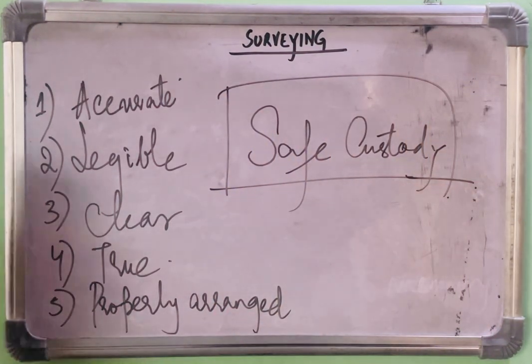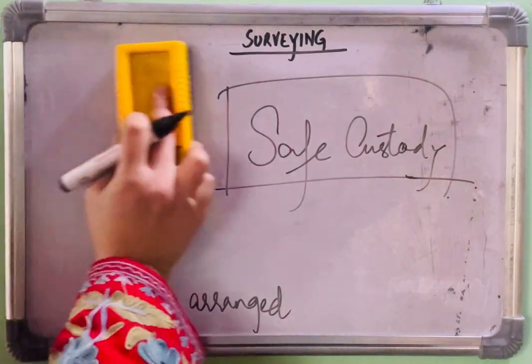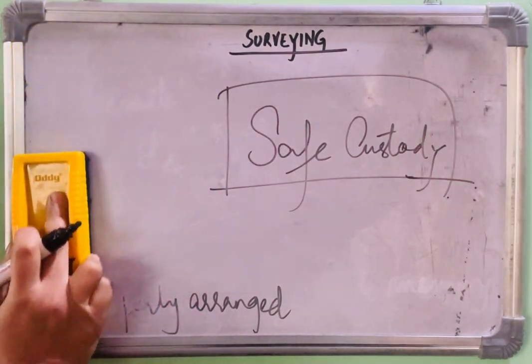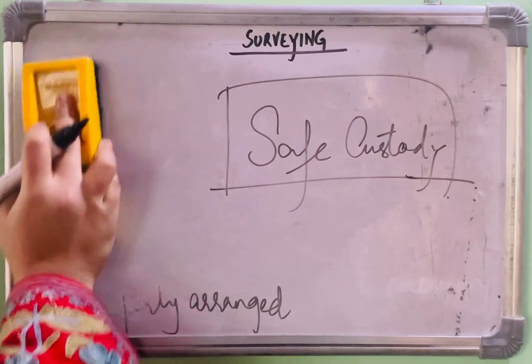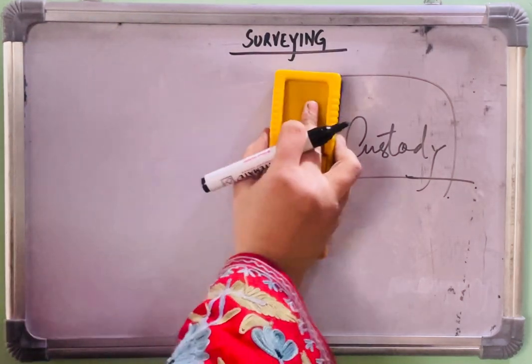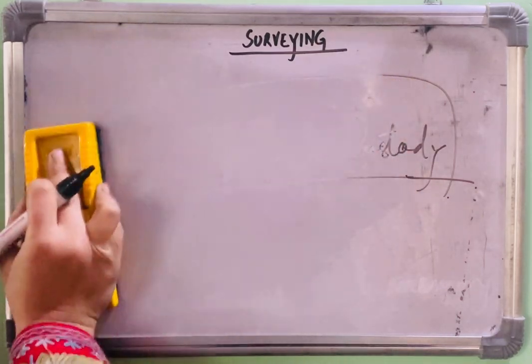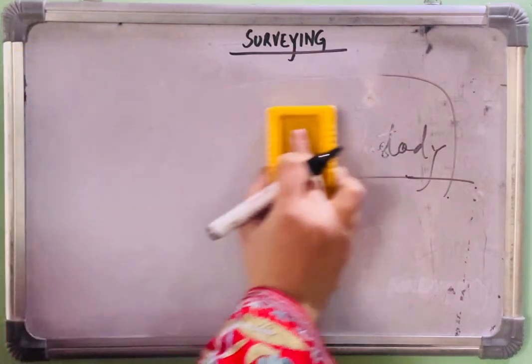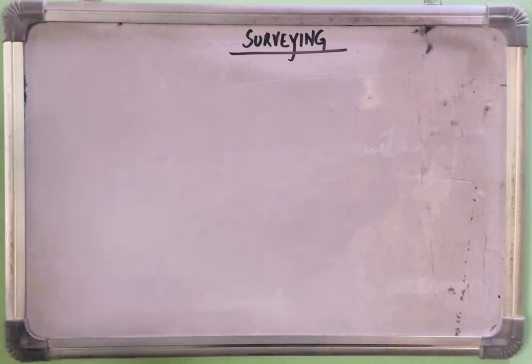So this was about the principles of surveying, wherein the first principle we studied was to always work from whole to part. The second was to always choose the method of survey that is most suitable for the purpose. The third one was to always make provision of adequate checks. And the fourth, the last one, was to always record field data carefully.